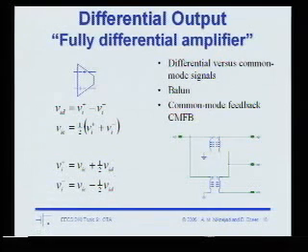Well, here's a practical issue. How do you actually generate differential signals in SPICE? There are actually a lot of ways to do it. You could use controlled voltage sources. You could take a single-ended signal and then split it into two with a controlled circuit. What's the issue with doing that? Why is that probably not a good idea? Let's use controlled sources.